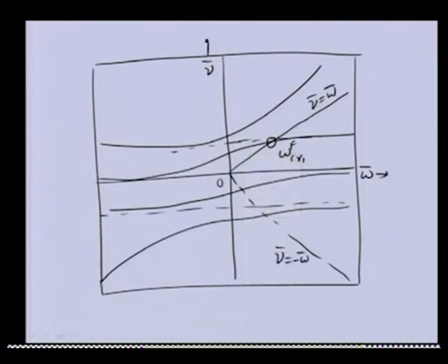then we will be having 2 more critical speeds. This will be the first critical speed backward whirl, this will be the second critical speed backward whirl. So, in this particular case we are getting 2 backward whirl critical speeds, but only 1 forward critical speed; the second forward critical speed is not feasible.